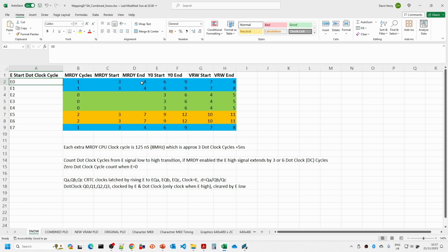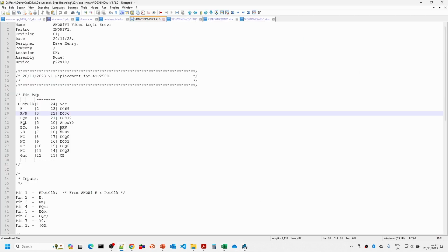And if we go back to our things here, we can see that there are various combinations here. We've got the combinations of things that we needed from here, and all I've done is simplify some of the rules so that we don't actually max out the number of connections. So you can see there's a 6 to 9, 9 to 12, 3 to 6 here. Some of the other ones were simple enough that they didn't need this aggregation, but this was necessary because we ended up with too many terms in the PLD configuration rules.